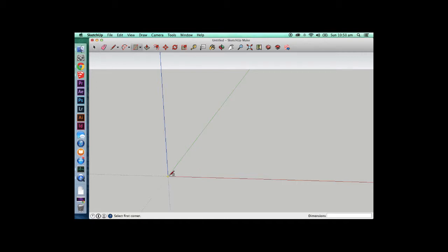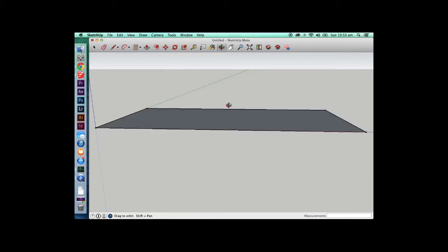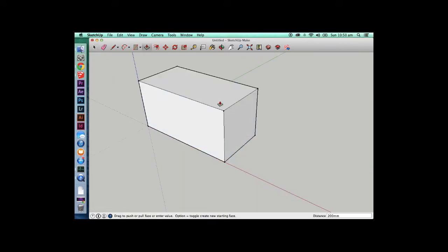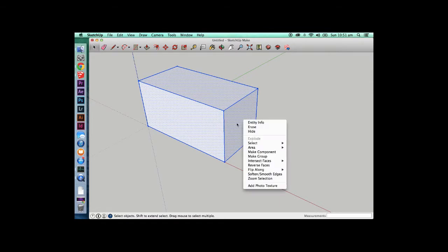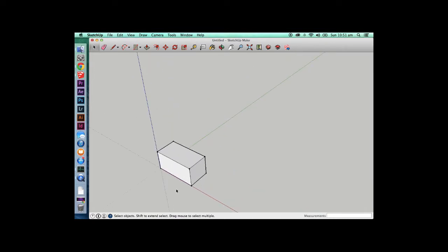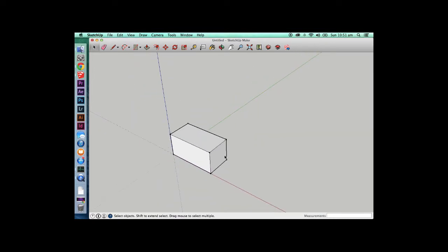So what we're going to do is start out with some basic tools and some construction techniques that are common. Where I am, we use concrete masonry block, which are 400 millimeters by 200 millimeters. We'll just zoom in on that. 200 millimeters high. In actual fact, they're 390 by 190, but you have a 10 millimeter mortar gap. Just going to group that. Now that is your basic building block for any house.